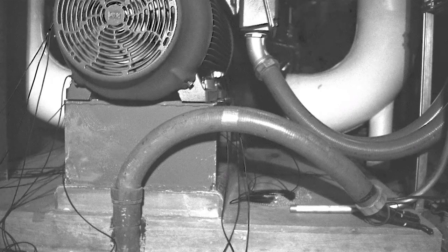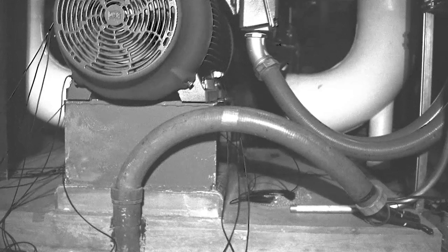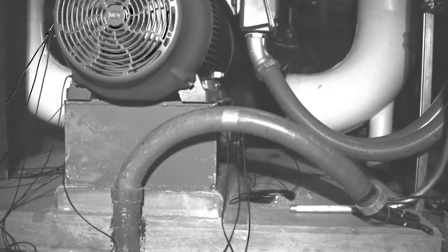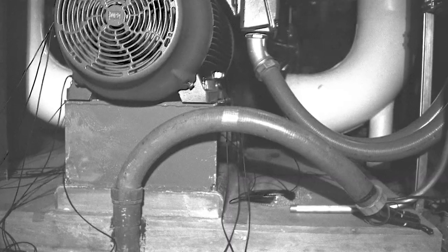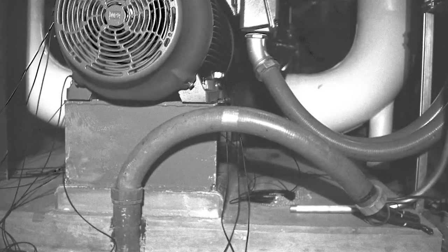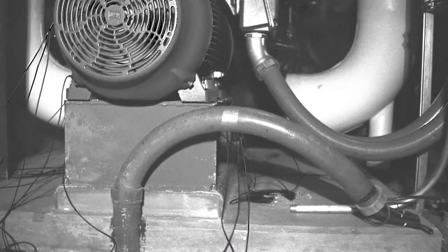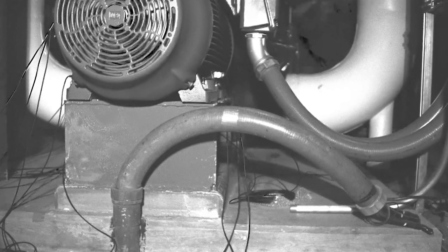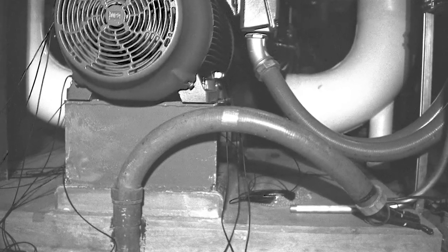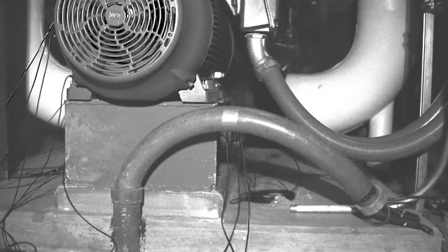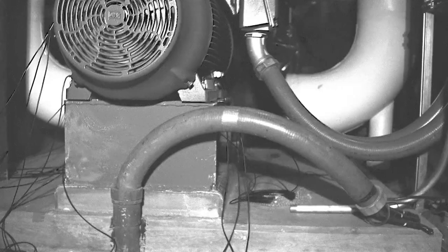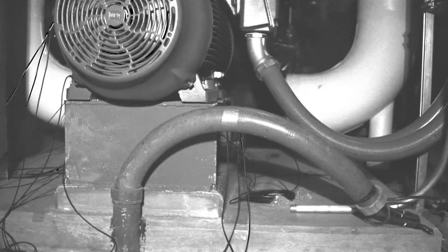The idea here is, right, being able to use a super high speed camera to actually visualize how the data actually moves, like how we're actually seeing movement. So in this case, right, it would not be very hard for me to defend the idea that perhaps the grouting and the base plate, this stuff is not put together well, right? We can see how this is openly rocking back and forth, but having this level of a visual aid for both the customer and the service provider, anybody, this makes what we're seeing in the vibration data that much easier.